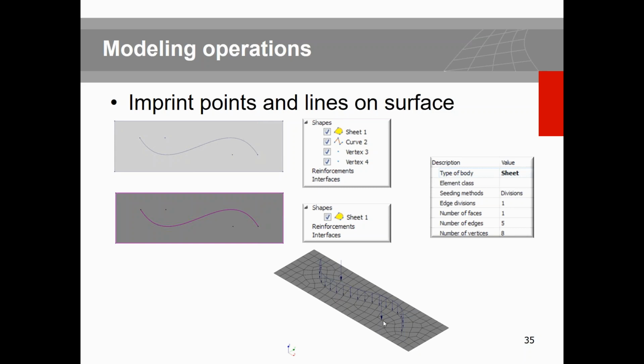The 2 point loads are available with, say, a vertical wall, so we model the wall based on the corresponding load. We need to know where the 2 points are, we imprint them, and then you impose the load on the imprinted edge and points, and you go through the process of loading.